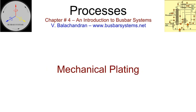Mechanical plating. Mechanical plating also goes by the name of peen plating or impact plating. It is an electroless process by which a ductile material is deposited over a metal substrate using mechanical energy. Copper, zinc, tin, and aluminium can be plated by this process. This process is suited for plating small components such as hardware and fixings.